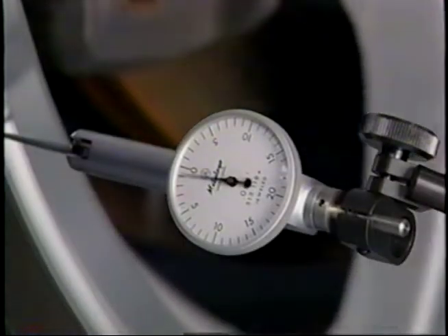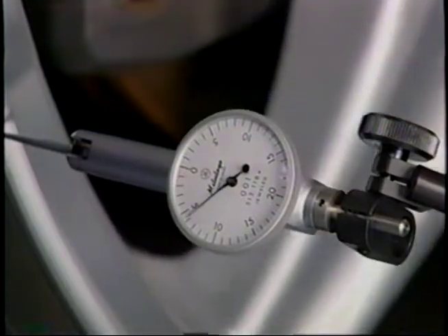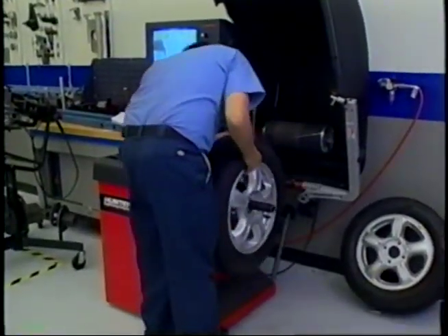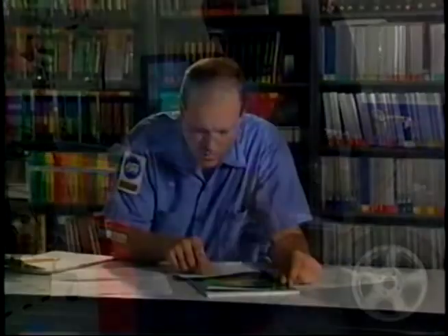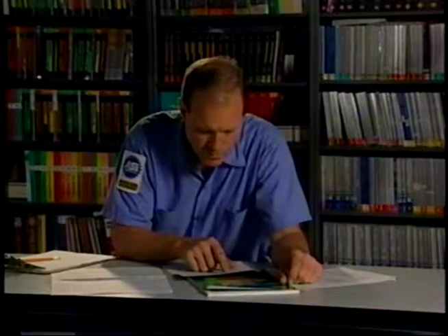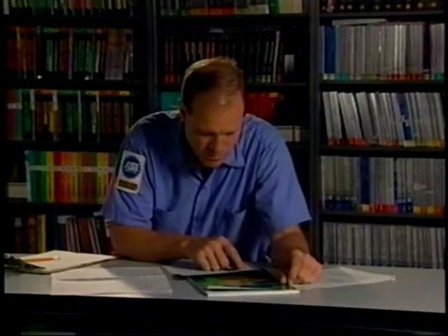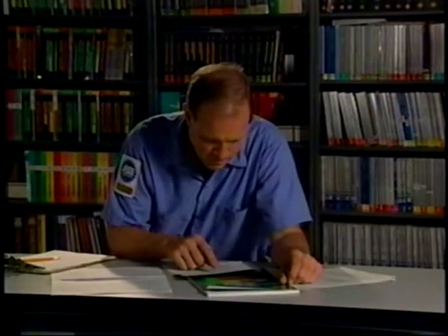If you are unsure how to check any of these problems, be sure to refer to the procedures in the service manual. With the exception of balancing, all of the previous problems will require new tires or the replacement of worn or damaged parts. A good diagnostic aid for tire wear complaints are the wear pattern charts found in most good service manuals or textbooks. You can save some time troubleshooting tire wear problems by using these resources.